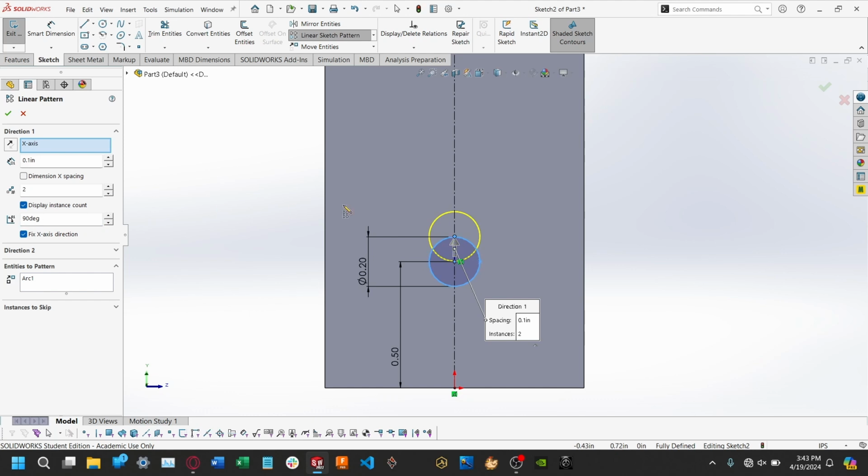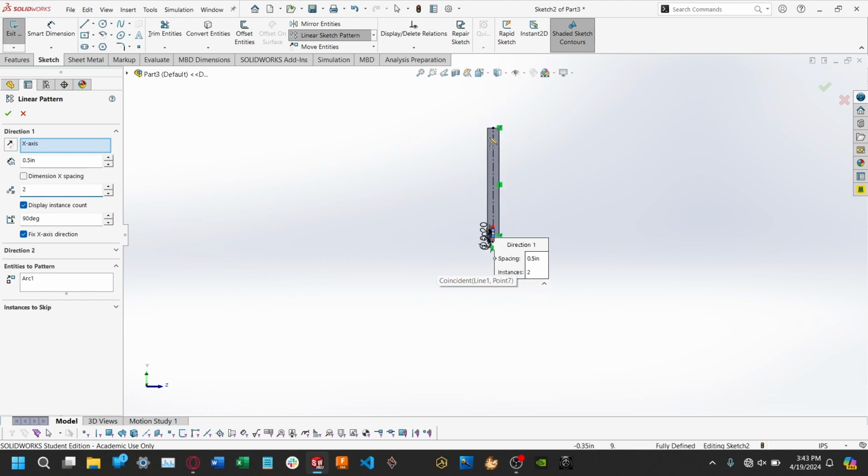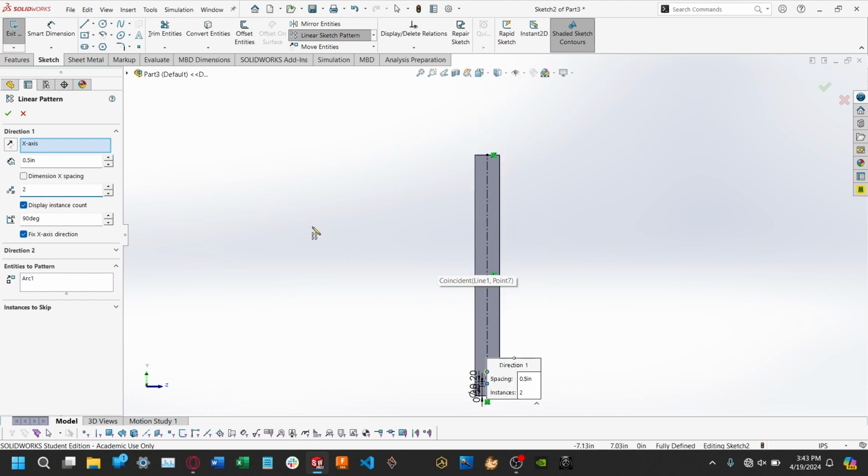It's a unit circle, so 90 degrees is up, 0 is to the right, 180 is to the left, and 270 is down. We're going to make the spacing 0.5. We used to make the spacing 1 inch, but something changed in our tubing convention. We used pre-made tubing instead of tubing that we'd make ourselves, and that was the hole spacing, half inch.